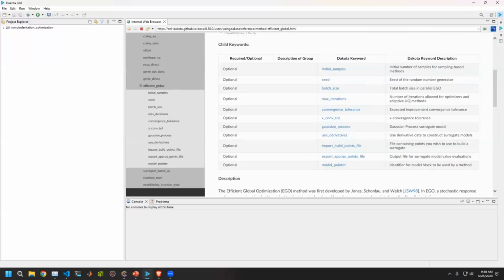And then on the QOI, that's a priori. So you know that I have an objective function that is measuring displacement, or I have a constraint function that's measuring maximum von Mises stress, and that's the quantity of interest. You know this a priori, but the solver is plugging those back into the file at the end of its execution for DAKOTA to then read.